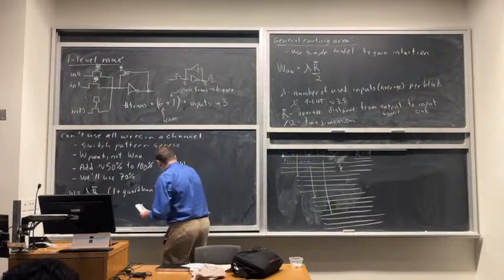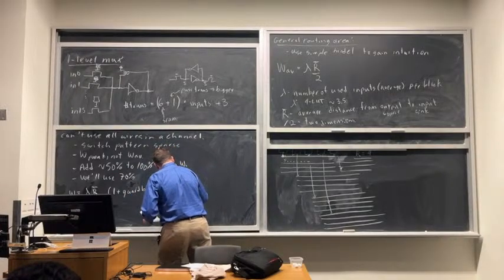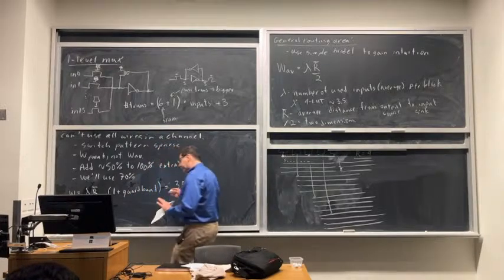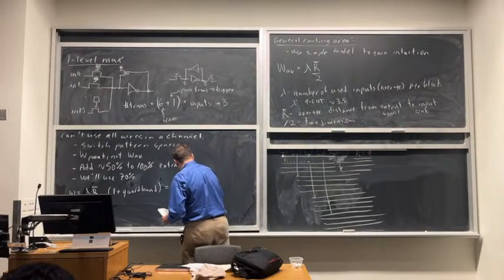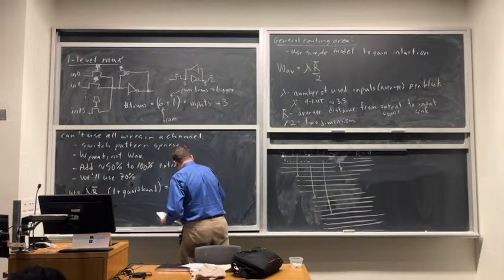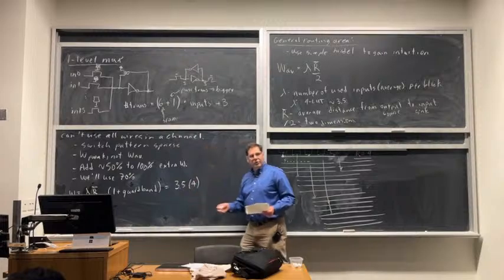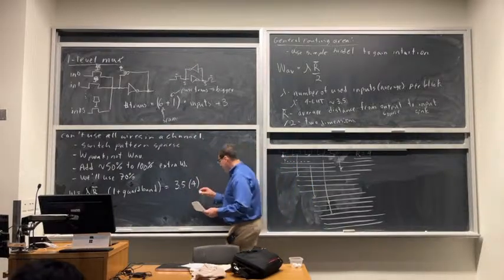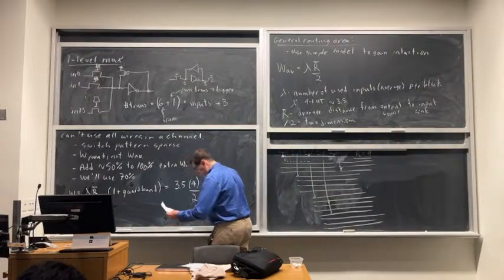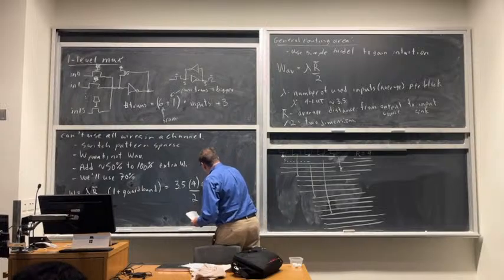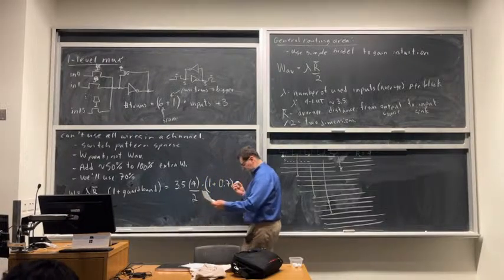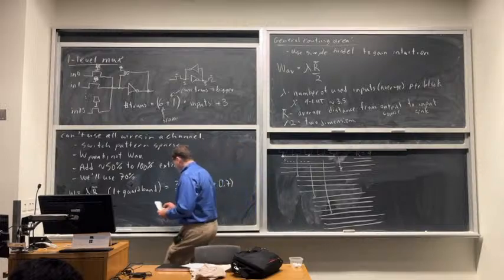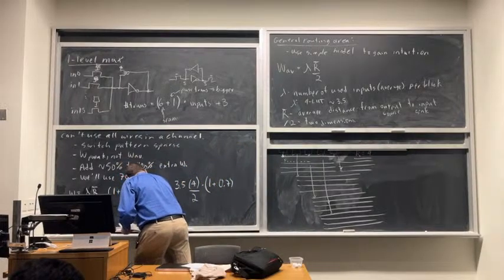If I plug in the numbers I already gave you, lambda is for sure no bigger than 4, but more likely about 3.5 for a 4-let. R bar, you have to run CAD tools to measure this, but I know it's typically about 4. Divide by 2 for the 2 dimensions. And then 1 plus, we chose a guard band of 0.7, which is reasonable. If we do all this, we get 12 wires per channel.